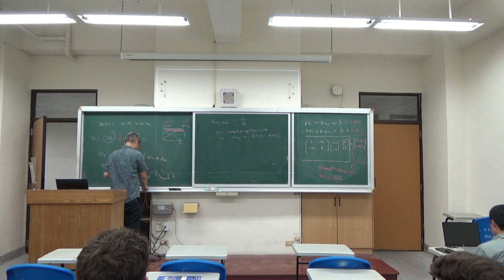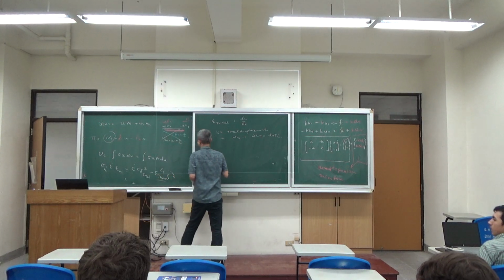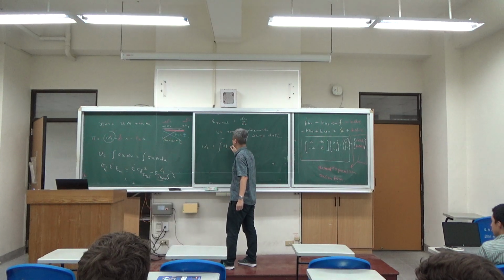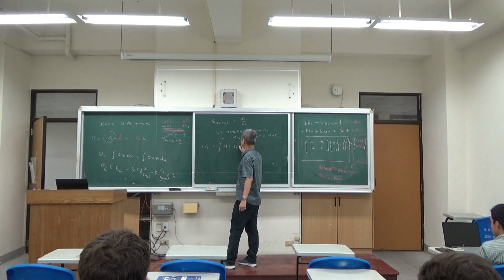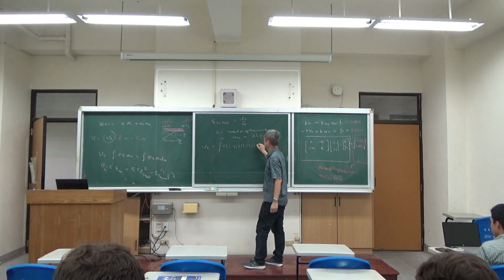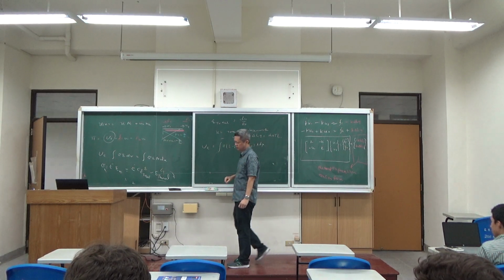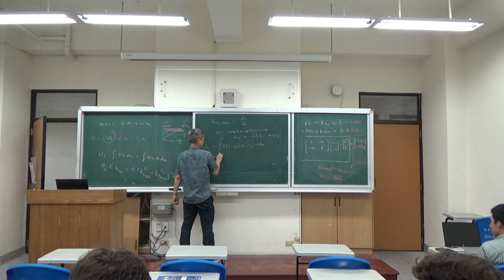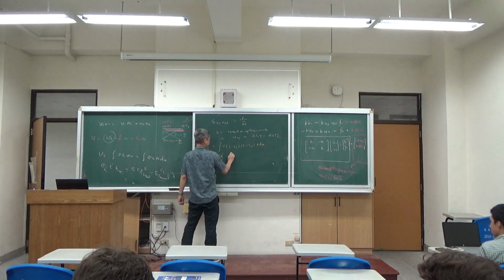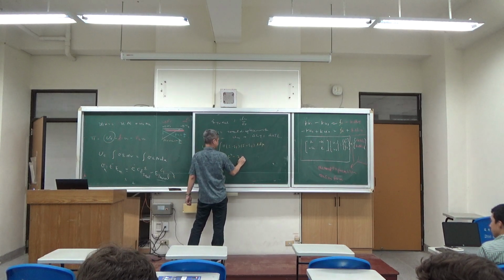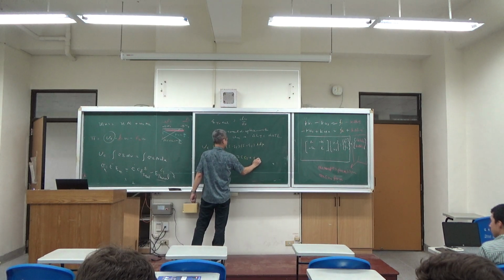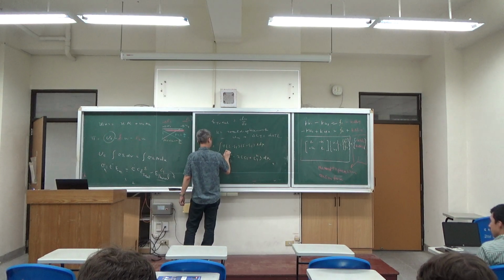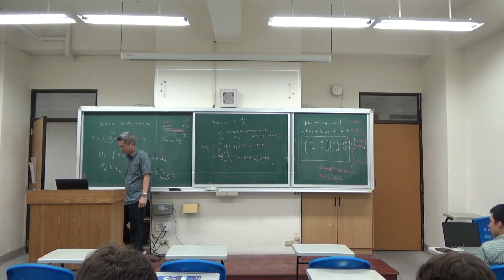Now let's come back to your total mechanical strain energy. It's going to be written as Young's modulus times the strain minus the thermal strain, times the strain minus the thermal strain, A dx. This expansion is quite straightforward. You have the EA and then total strain squared minus 2 times total strain and thermal strain plus thermal strain squared. So this is what you have.